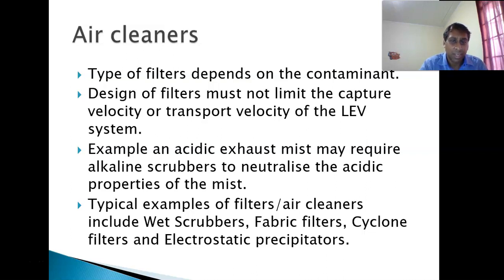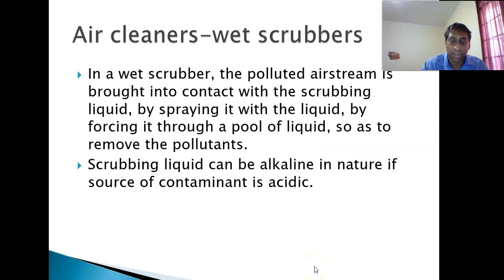So I guess a good idea is to learn some types of the scrubbers. So I have some here, air cleaners or wet scrubbers. In a wet scrubber, the polluted airstream is brought in contact with the scrubbing liquid by spraying it with the liquid, or by forcing it through a pool of liquid so as to remove the pollutant. Scrubbing liquid can be alkaline in nature if the source of contaminant is acidic. Again, maybe a kind of blurred picture if you have never seen a scrubber in real life.